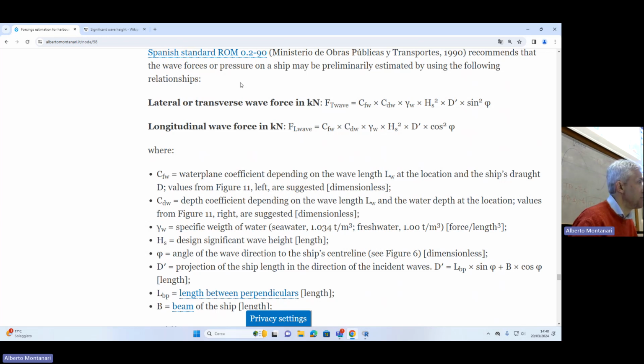It's basically an up and down, so there is no drag, or drag is very negligible, because there is no movement of the water with respect to the surface of the ship. We will see that with currents there is indeed a drag force, because currents are a movement of mass. But with waves, you don't have movement of mass.